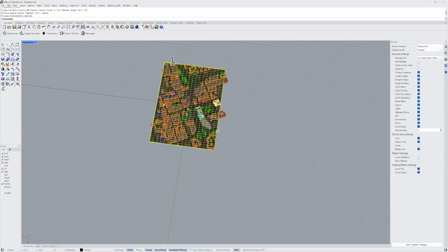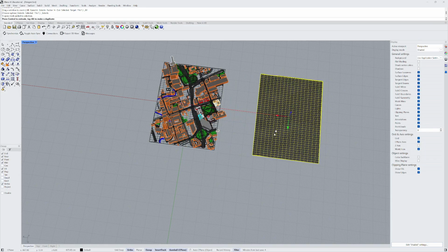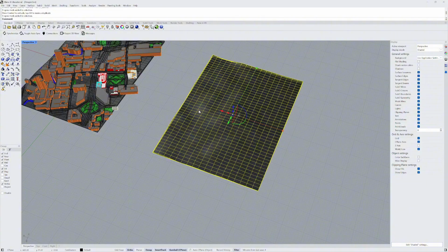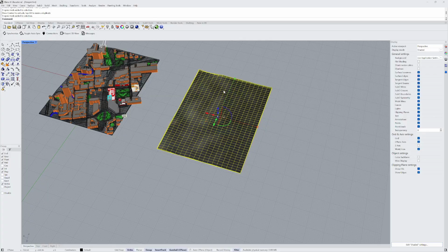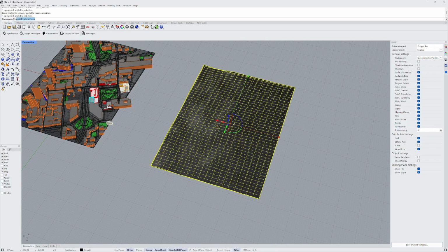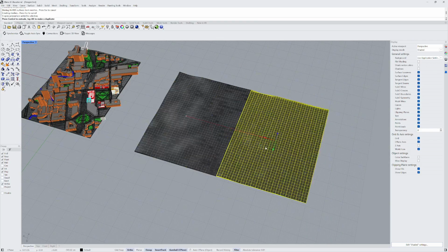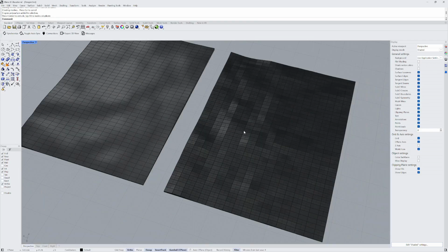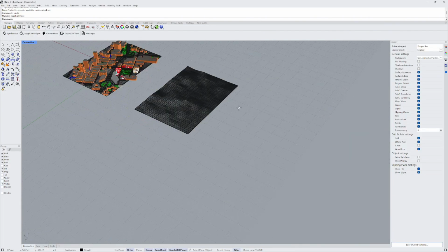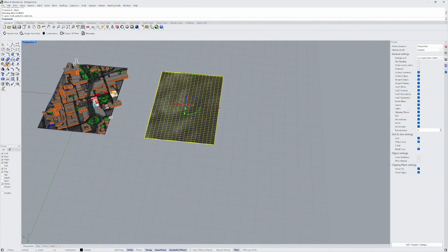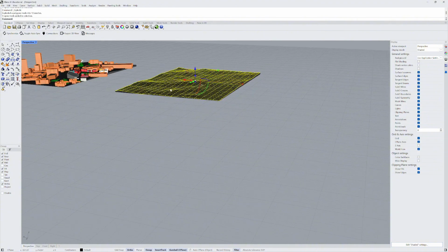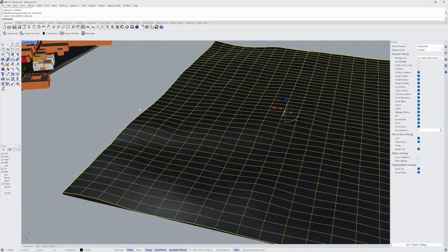Now, if I wanted to create a new file, because this is now a mesh, if I click on it, it tells me what it is up here. It's one open mesh. So let's say I wanted to create this as NURBS. If I just do mesh to NURB, you're going to see that it's not going to be very clean. It's going to be lots and lots of NURBS faces, just like little squares. I don't want that. I want something a little bit better. So what I'm going to do is select this face and explode it. I'm going to use this top mesh face, and I can type patch.